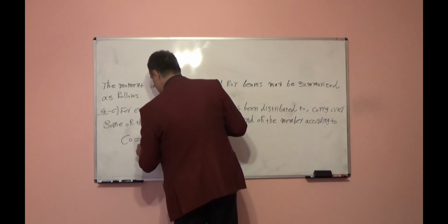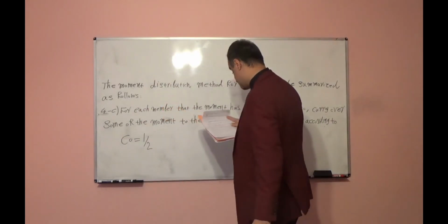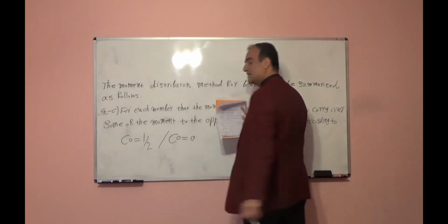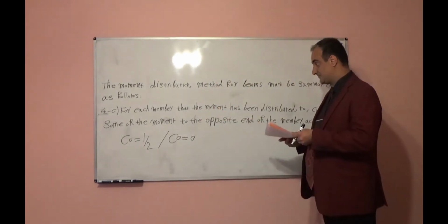If it is a fixed side, it is 1/2. If it is a hinge, the carryover factor is 0.